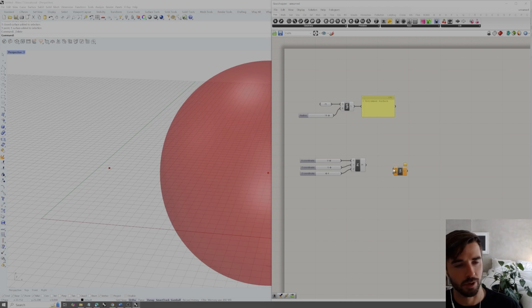and we can double check what the inputs and outputs from this component are to get a better understanding of what the component requires in Grasshopper. So we need a starting point of this line, which requires a point parameter, and an endpoint of this line. So we could either construct 2 unique points in Grasshopper, or we could reference 2 points from Rhino.